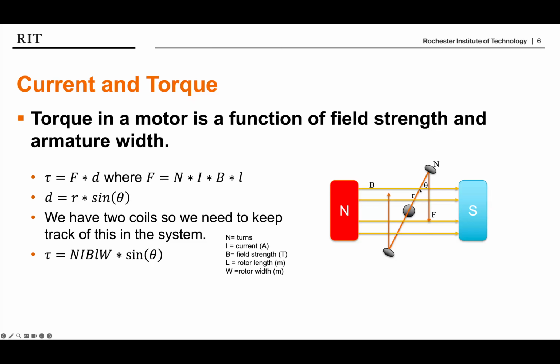So that might vary with rotation of the motor, but as that varies, I have another angle over here that's also varying. And we can now begin to see why we might have a different number of either magnets or coils, because if I were really clever, I'd stick on at least one more coil so that as this angle decreases, this angle maximizes, as this angle maximizes, this angle decreases.